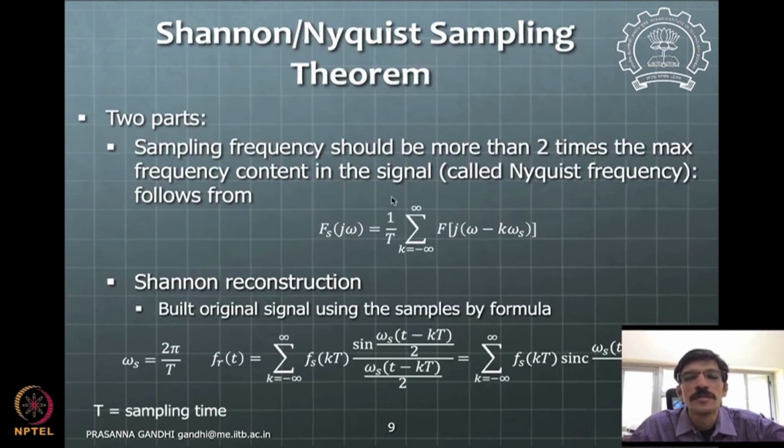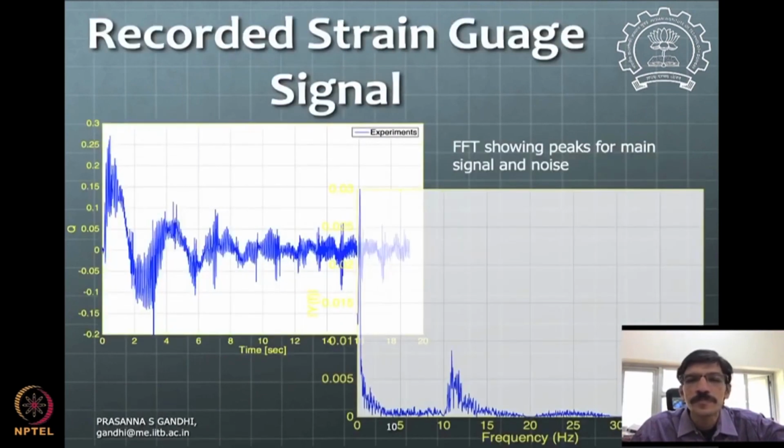The signal needs to be sampled at least twice its frequency content to get it to the final digital form, which represents the original signal content. If it is not done, then the signal contents are all lost. Ideally, we will need about 3 to 4 times the sampling frequency to really represent it in the practical scenario.